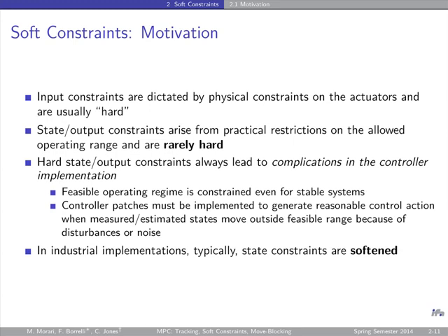Instead of having one constraint, one horizon n, remember we had this one horizon n, I choose different horizons for different parts. For example, I will choose one horizon for my outputs, that's the horizon ny. So I add up those terms only up to ny. I have a different horizon for my controls, nu. This controller is between some u min and u max, but only over some horizon nu.